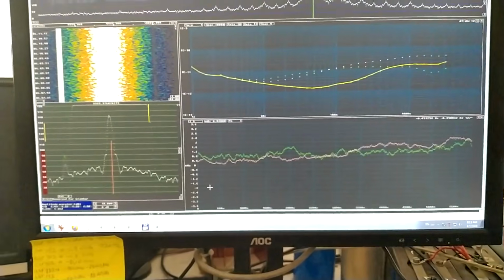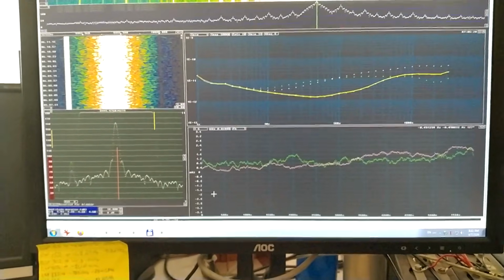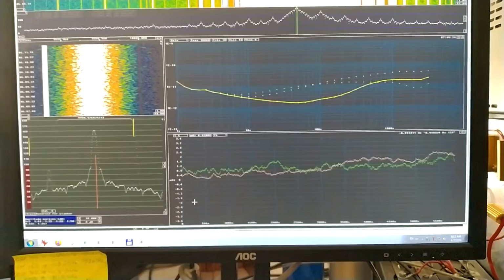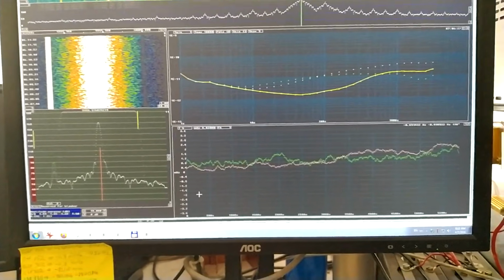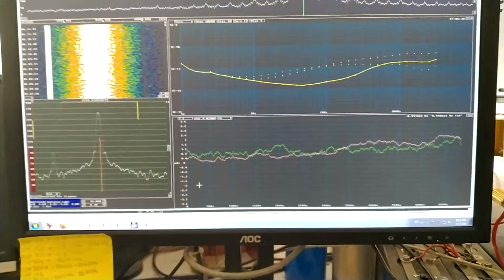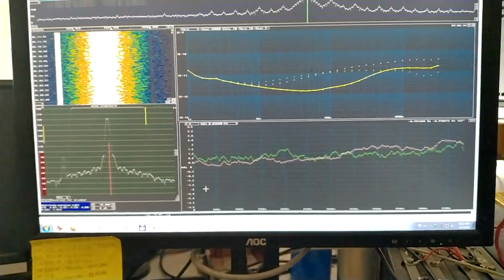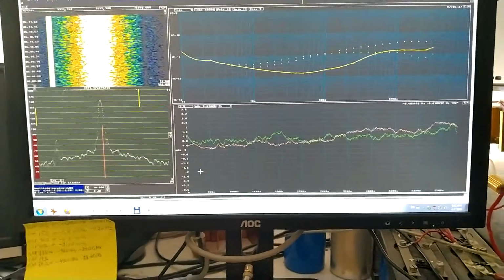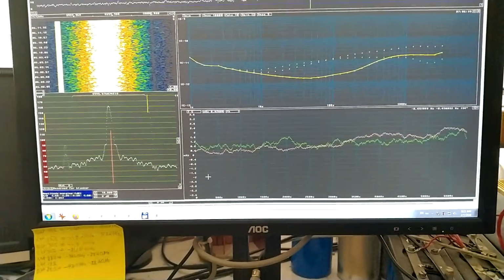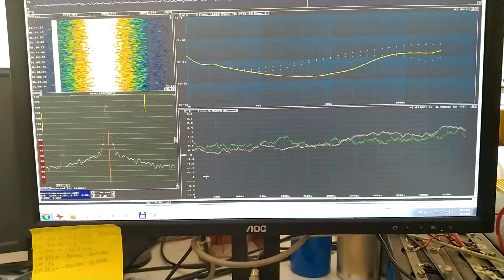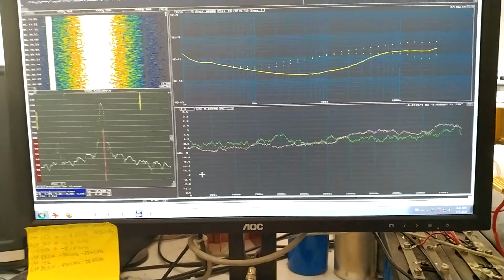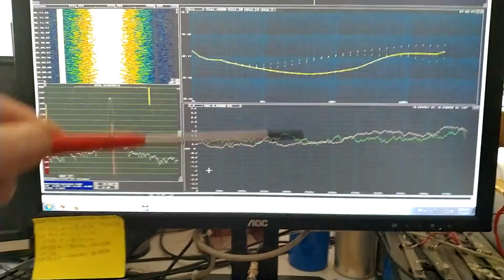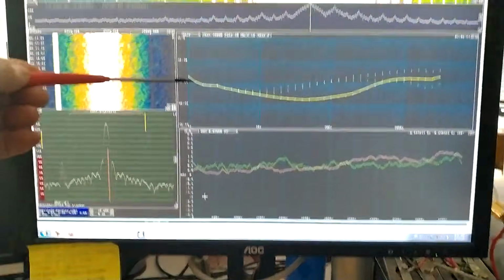And the noisiness is very different from the 2 oscillators. I don't know the source, maybe the power supplies are not very good on them, and it doesn't really matter because these are slow variations, 5 seconds per point, so I'm interested in frequency changes over ranges up to 2 points. You can see the Allan deviation.